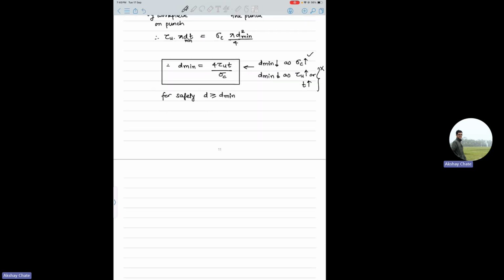And sometimes, apart from minimum clearance, you have some allowances. Along with radial clearances, some additional allowances are given. So in some questions, if you see something like this, then no need to worry. Basically, you have to write again for punching and blanking separately.